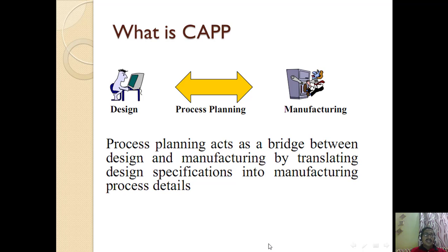So here expert knowledge is not required, whereas earlier in the traditional approach, knowledge of the capabilities of existing machinery was also important. Let's say you are going to design a process plan without any computer, so you must have knowledge regarding the manufacturing parameters, process parameters, and their conditions and constraints: how it works, what the limitations are, everything you should know, and only then can you plan properly.